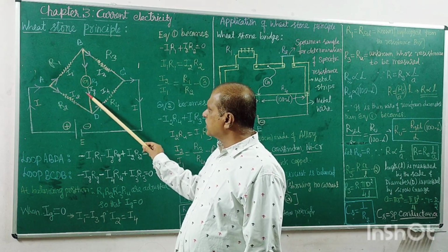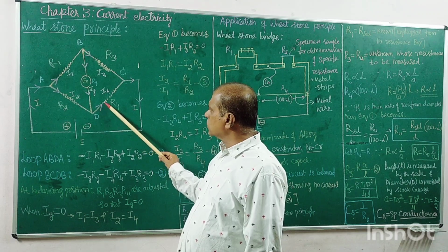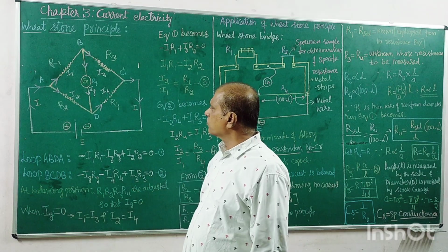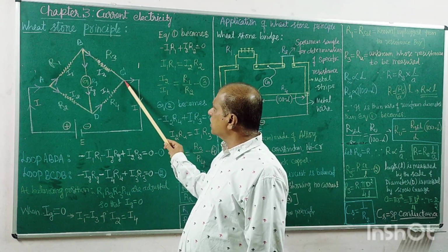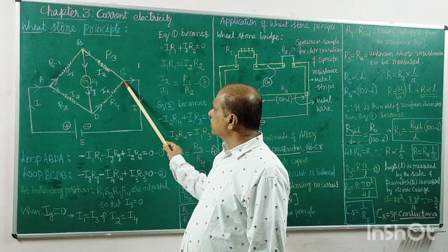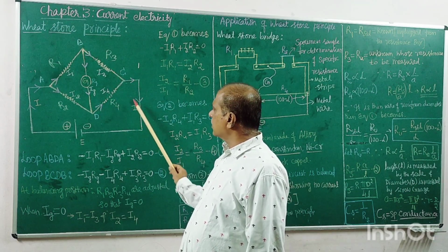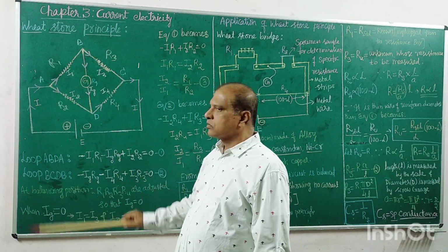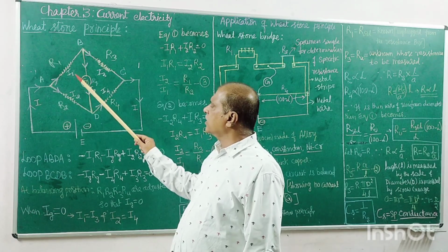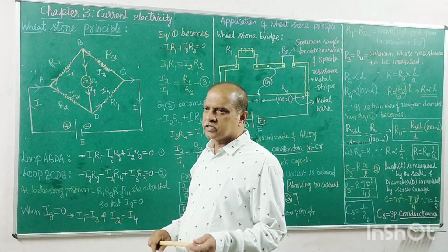So this plus this gives us I4. The amount of current flowing through this conductor is I4, having the resistance R4. And at this junction, these 2 currents arrive and merge into one current again, adding up to I, back to the circuit. So this is the direction of the current at each junction, in accordance with Kirchhoff's law.